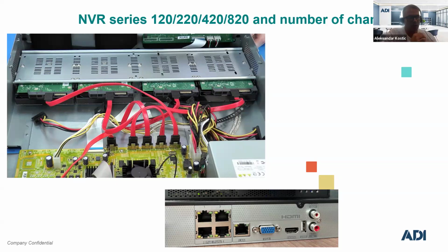When we speak about network organization, I mentioned briefly in the beginning that video surveillance, in order to have reliable network connectivity and not significantly affect the network performance, needs to be isolated to its own network segment, like a VLAN just for the CCTV system.